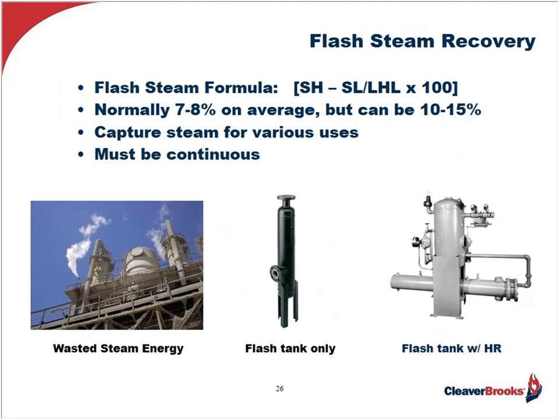Why not recapture this energy, if it is continuous, and pipe it to my deaerator for removing oxygen and carbon dioxide, and at the same time recoup some of the hot condensate BTUs from that condensate which didn't flash, putting them into the makeup water stream before dumping this condensate into the low pressure return line. Sounds practical, doesn't it? Unfortunately, this idea is seldom employed unless attention is drawn to it and the cost is justified.